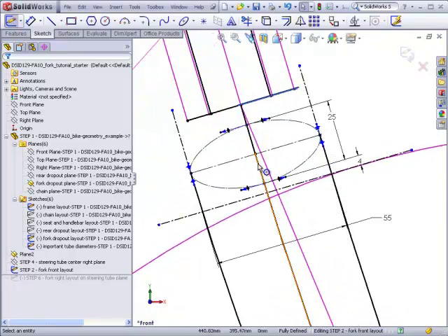You can also see that this middle guide is ending on the center of the steering tube. I've made my cross-section so it's 25 millimeters tall, 55 millimeters wide, so it's a little bit wider than the crown where it's going to join the head tube of the frame. You'll notice that I've drawn this as an oval, but I've turned this into a construction line rather than solid